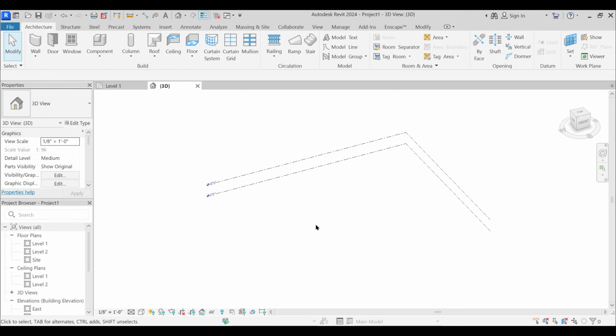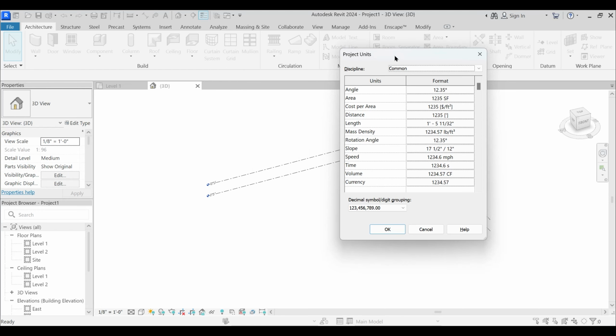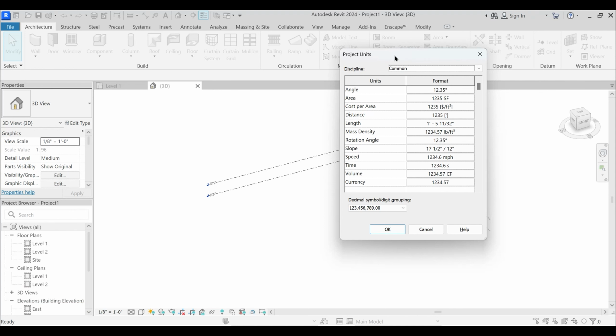So the first step after coming to Revit is setting up levels. But before that, fine, sorry. Before that, the first step is that you will set the units. Fine. As I said, working in Revit is multidimensional. You can switch between working units anytime. That is from imperial to metric or metric to imperial, vice versa. But for this course, we will be working in the imperial system, that is feet and inches.